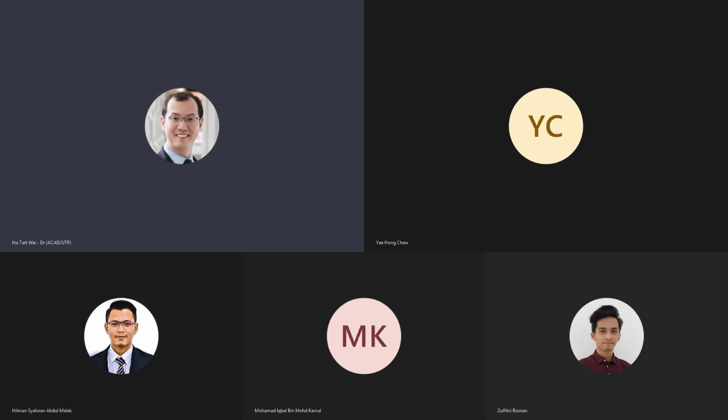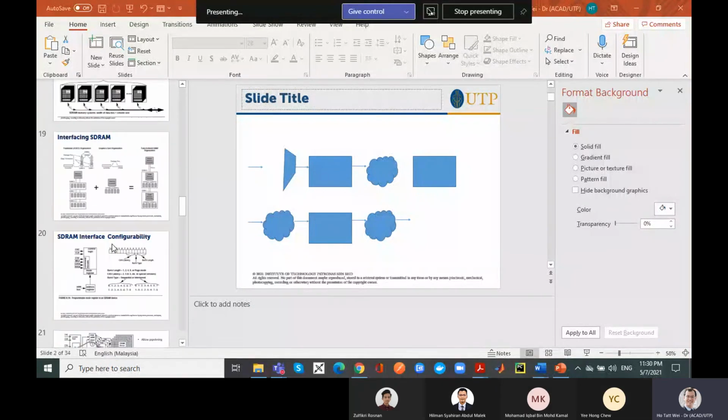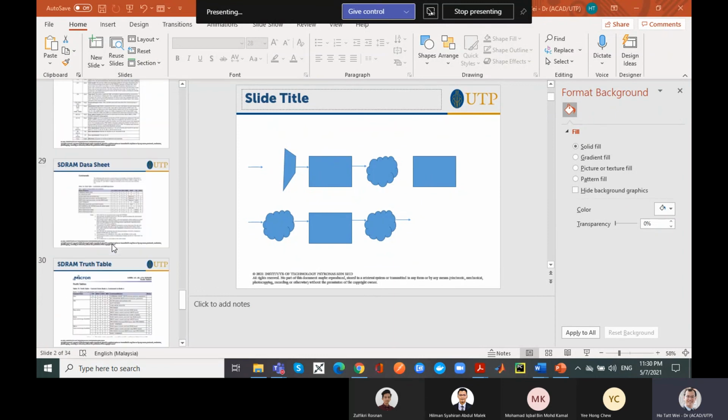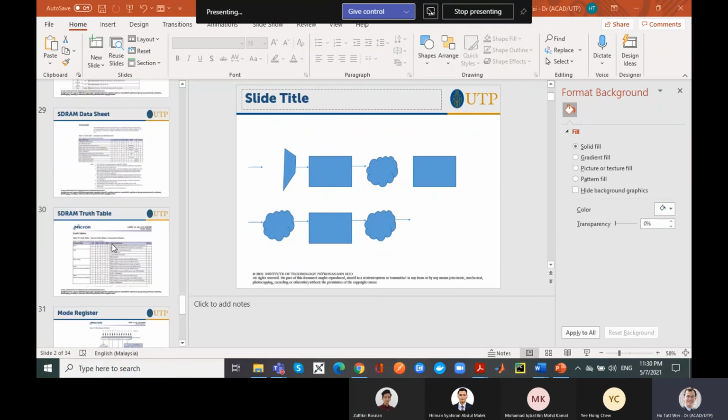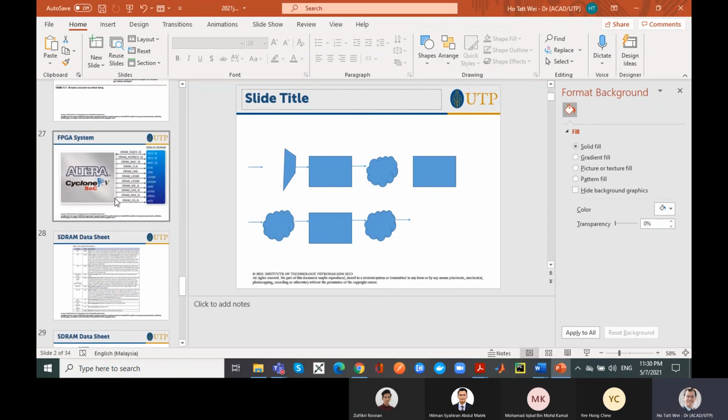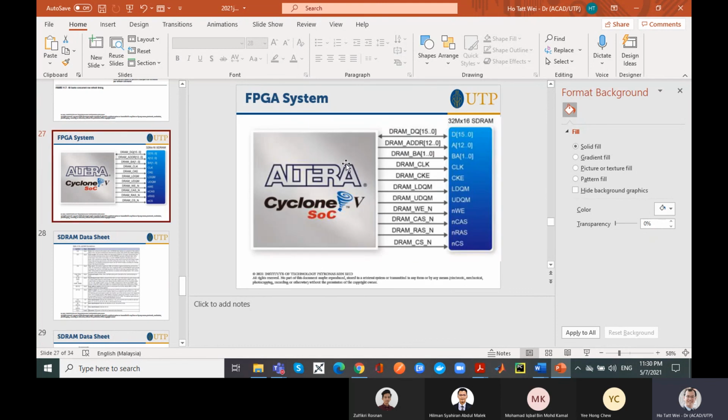Yes. Okay, sorry. What I meant was the important part for the FPGA. I'm going to give you the long story on Friday, what the FPGA is and all that. But the important part really is you need to know this is your SDRAM chip. It's connected to which pin on the FPGA. This chip, which pin on the FPGA. So you make sure that you have a constraint file that specifies this pin number needs to go to what signal name, the DRAM DQ signal in the FPGA. Once you set that, that's the most important part.